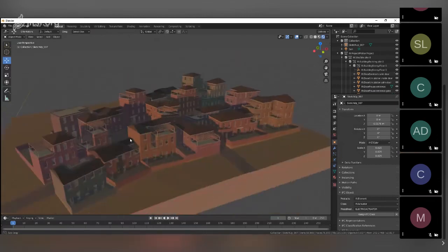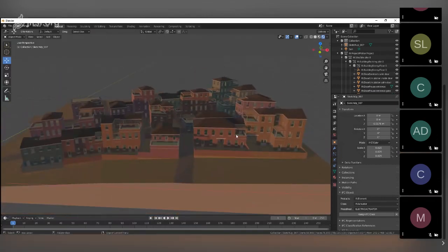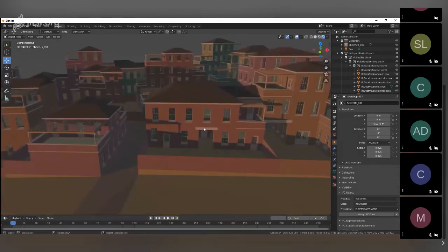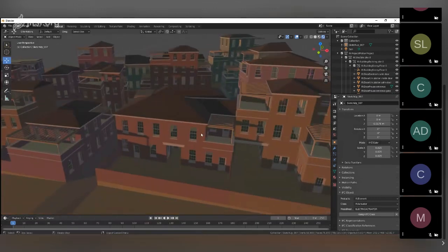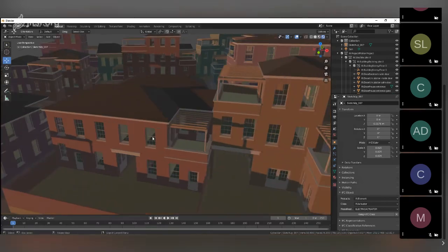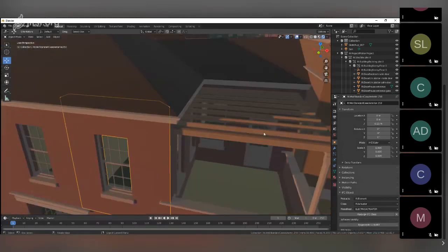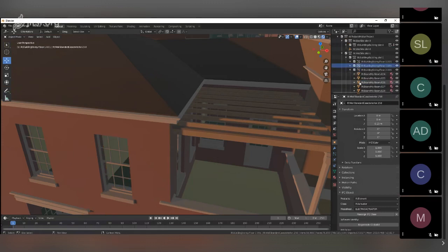So what I've done here is I've generated an IFC file and imported it using Dion's Blender BIM IFC importer. As you can see, up at the top left, it's an IFC wall, and we have the entire structure of the building. There are 19 plots, and there's one building per plot, and we have the whole structure of building stories.